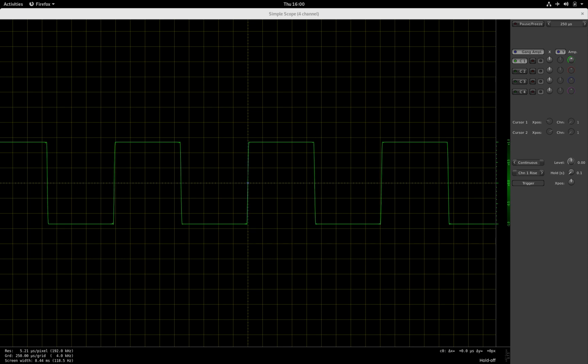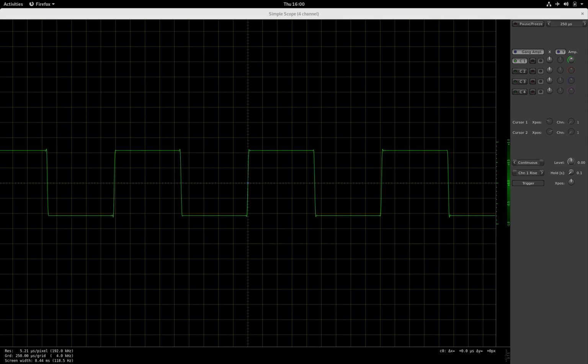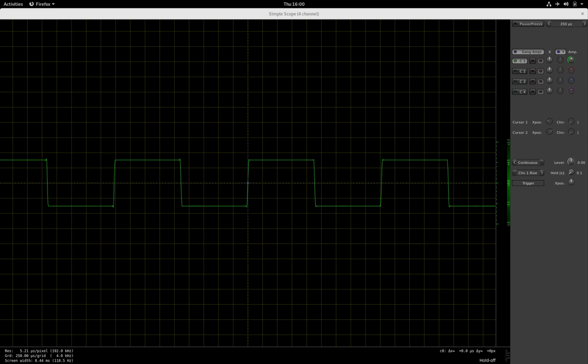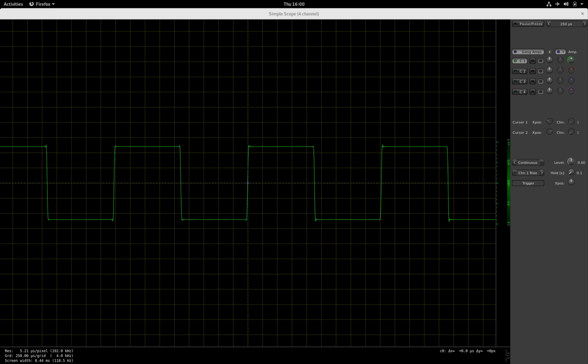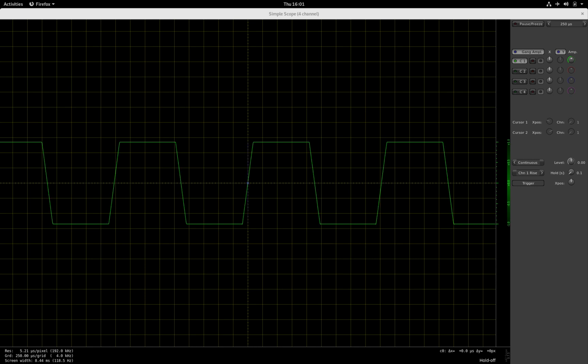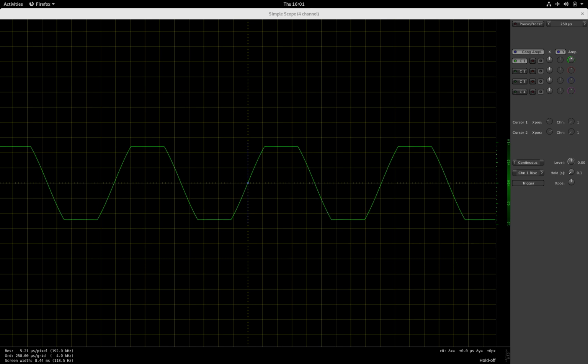The effects unit also has a level control, and as I move the level control down, as with the overdrive effect, the output signal will only be reduced in signal amplitude. And if I move the gain value down, of course the clipping will get less, and with less clipping I can then adjust the signal amplitude with the level control. Okay, so that's basically what a distortion effect does.